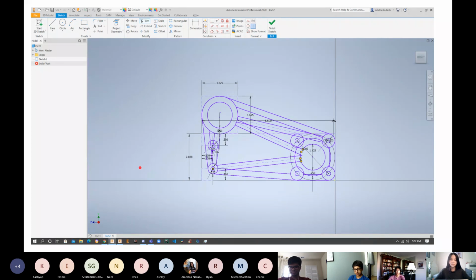So what we do for some of our parts is we cheese it, that's what we call it, which is basically if we want to cut out material or lessen the weight of our part, we would do a bunch of offsets around the holes and make connections between them.